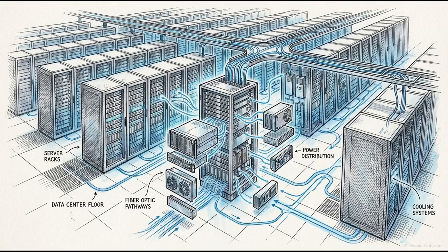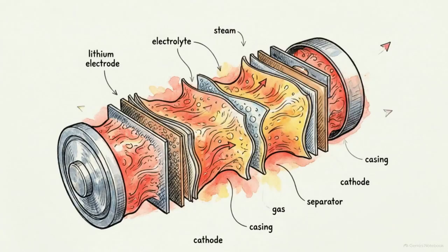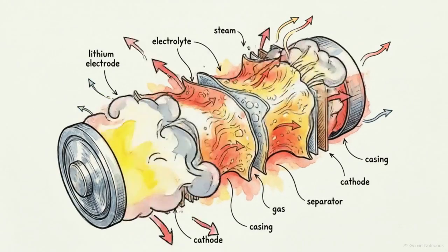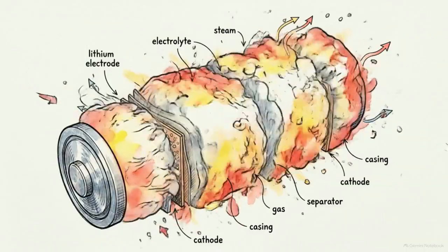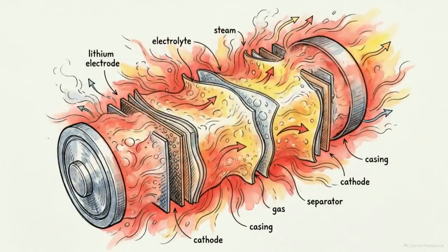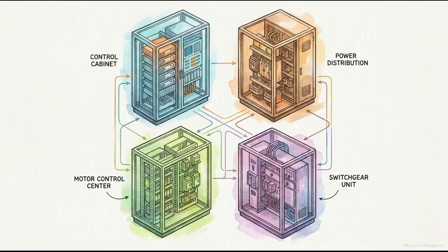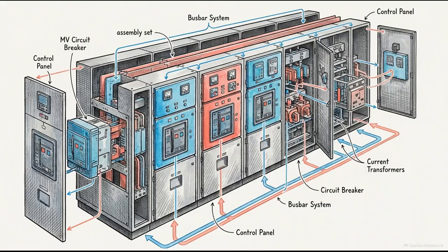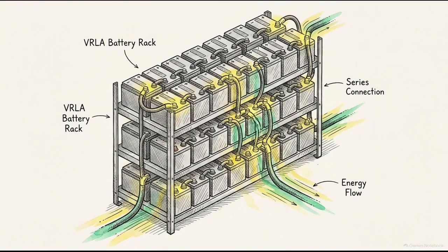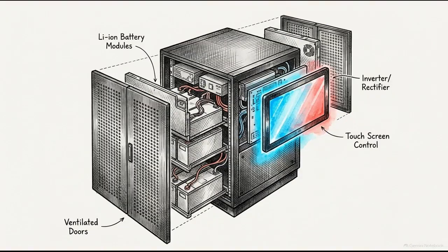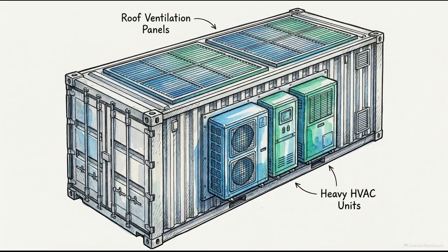Inside a data center, the threats to critical power are entirely distinct. A high-energy arc fault behaves nothing like hydrogen gas accumulation, and neither resembles the chemical sequence of a battery cell entering thermal runaway. Protecting a facility requires securing 4 specific environments: medium and low voltage switchgear, VRLA battery strings, indoor lithium-ion UPS systems, and outdoor battery energy storage systems.